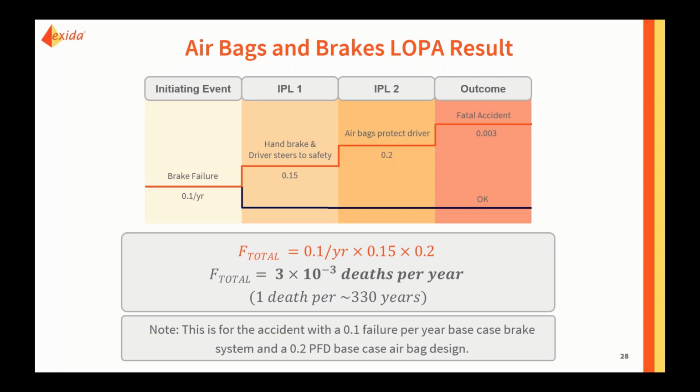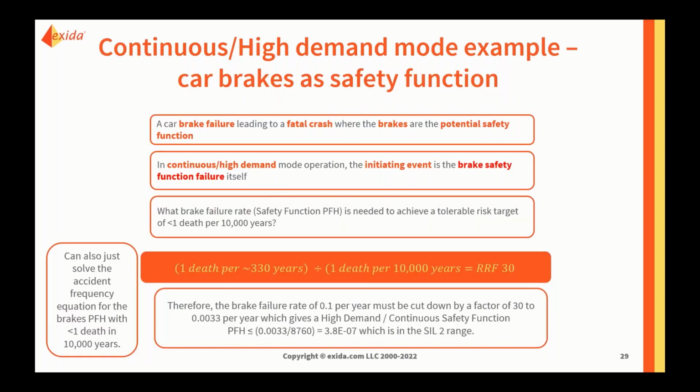Now, there are 2 different potential safety functions that we might consider here. The first case that we would consider in our LOPA analysis is the brakes themselves. And since the brakes are our initiating event and we're using them all the time as we drive, they absolutely fall into that high demand and continuous mode definition of safety function.